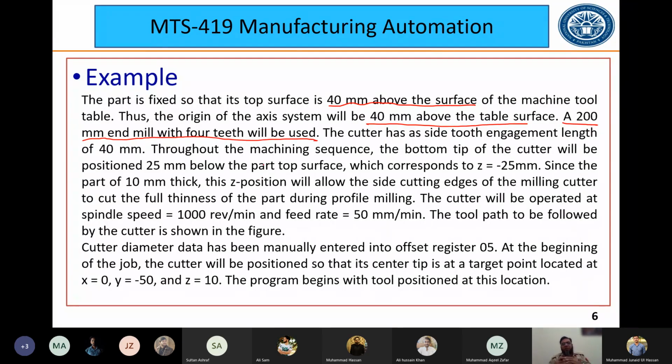The end mill means that you need to carry out the cutting from the edge of your workpiece. So this is your workpiece, and you have to cut the edge of the workpiece with the help of your cutter. As you can see, the movement of my fingers is the tool and my left hand is the workpiece. This is the movement which will carry out the cutting of the sides. Okay. All right. So this is all given in this.